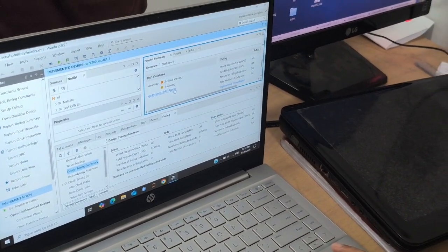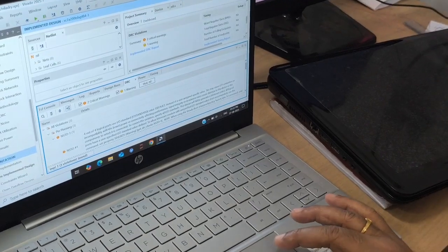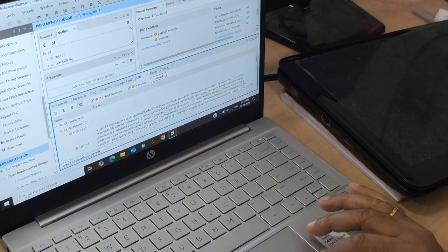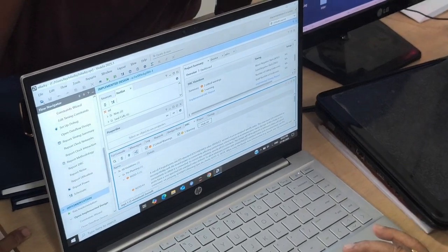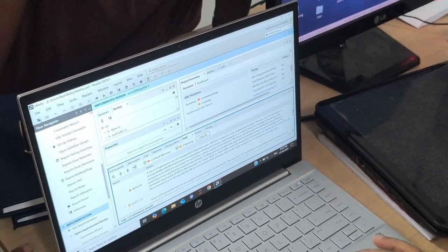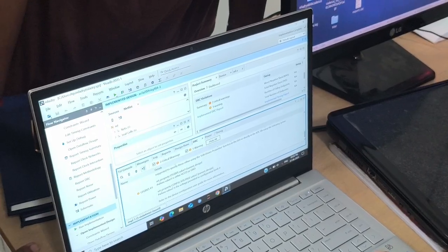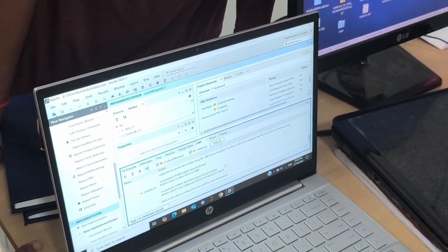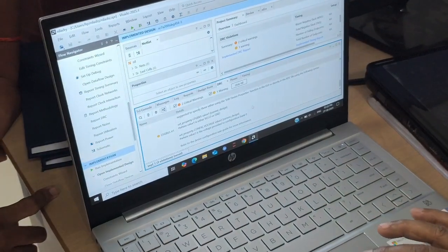So the implemented DRC report you can also see from here. These are the 4 out of 4 logical ports, IO standard and default. These things you can read from here. They are telling how they have mapped the logical things, ground and voltage, everything. They are telling which port is mapped and what the information is regarding it.